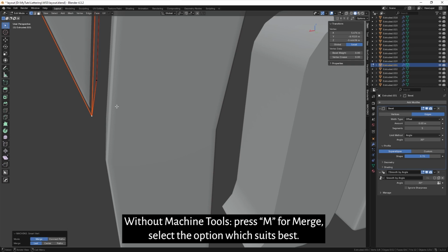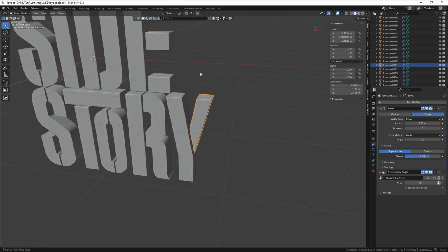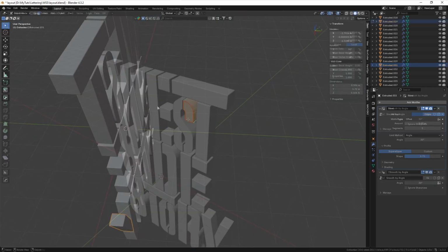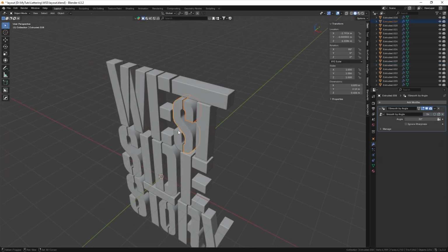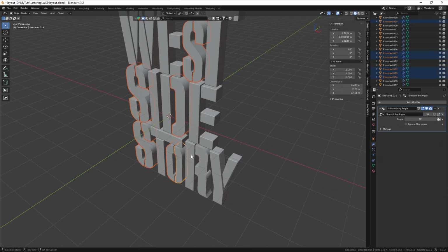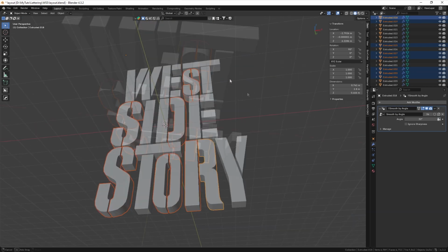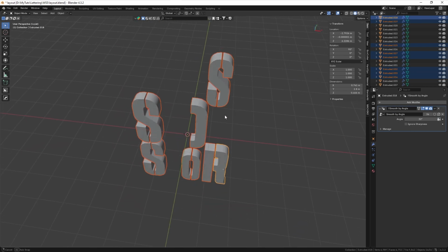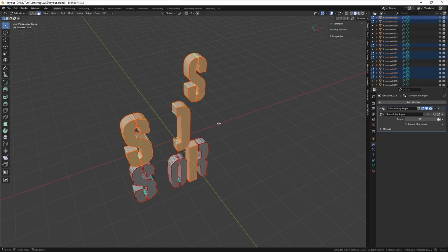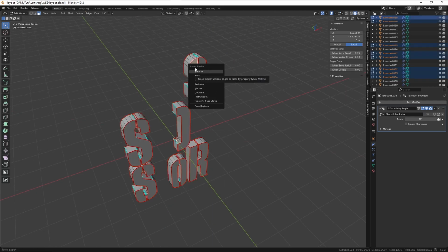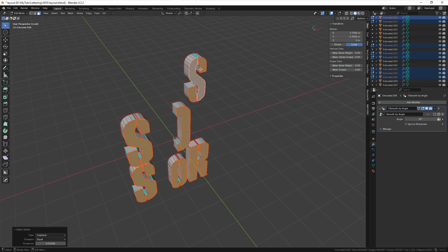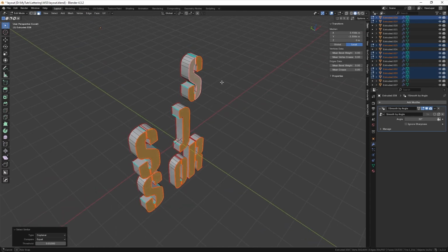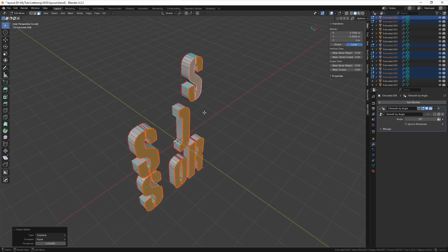If you have machine tools, let's see if there are any other parts which look weird. And now let's take all these round parts and prepare them for the SubDiv modifier. So select all of them and press / so we can isolate them. Select all of them, go to face mode, select one face and Shift G for selecting similar, in this case coplanar. So we select all the faces which look into the same direction as the one we have selected.